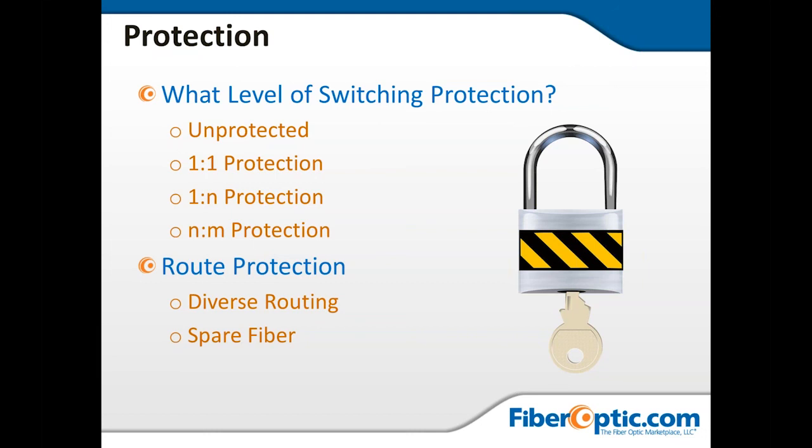And then you're also going to want to look at spare fibers. However many fibers you think you need today, I recommend you go 4 times. If you think you need 12, do 48. It's easier to pull a 48 now and have extras than to try to pull another 12 or 24 next year. Then you've got whole routing issues. You've got extra labor. It's cheaper just to go ahead and pull it once and be done. If you need 72, pull 144 or 288.